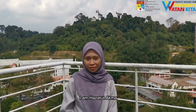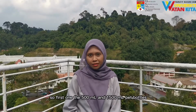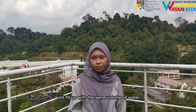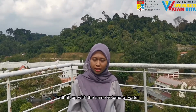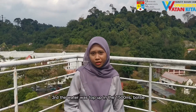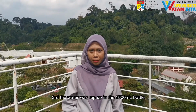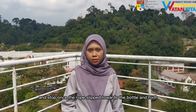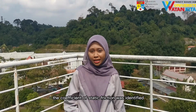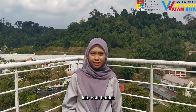I am Hazatul Akma, and I will handle the methodology part of this lab. First, the 500 ml and 1500 ml PET bottles were filled with the same volume of water. Second, the bottles were hung on the fixed drum. Third, water was poured into the 1500 ml PET bottle and stopped once the rope slid towards the bottle. And fourth, the coefficient of static friction was identified by using the difference of the volume of water in both bottles.